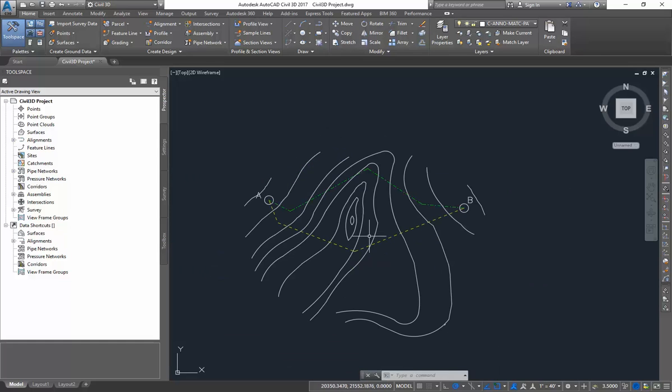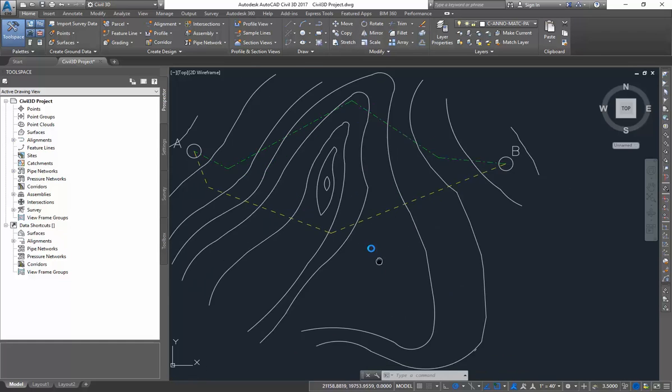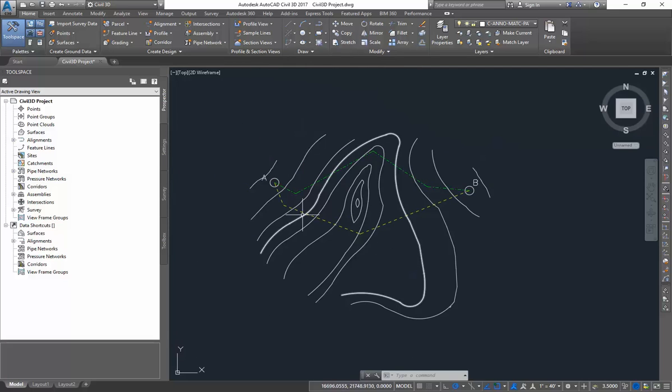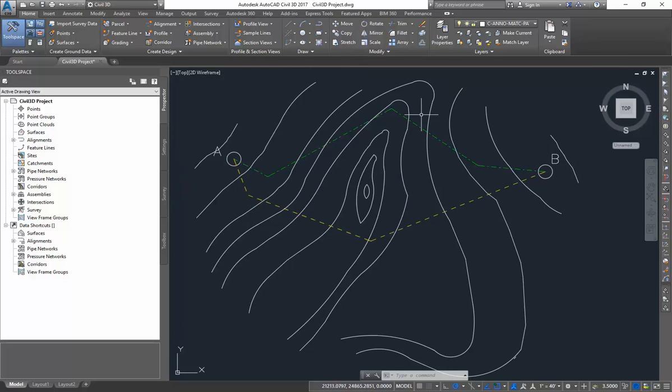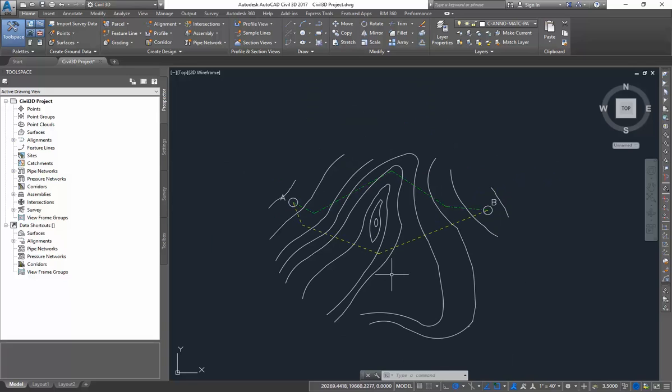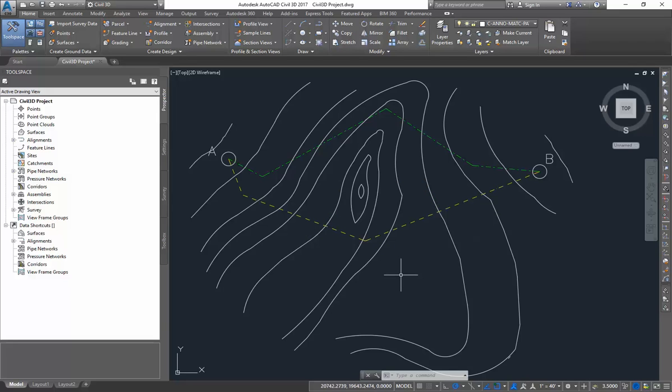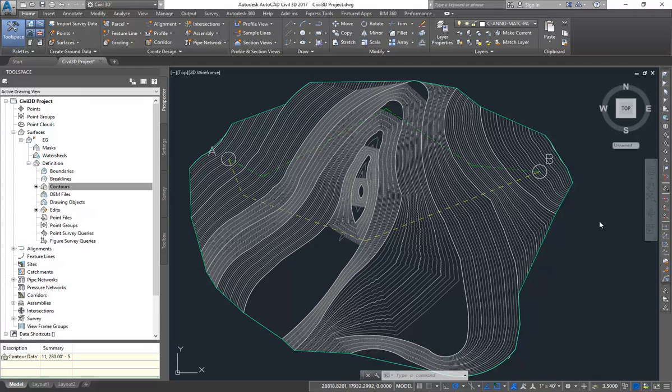There's a little bit I want to lead you through with the alignment steps, how you define an alignment. In this case, we're not going to define by objects. We're going to define an alignment using a more sophisticated method, so I'll pick up on the video at that point. For now, go ahead and define your surface, show it as contours to verify that it looks correct, and I'll pick back up when you're ready to define the alignment.